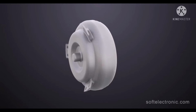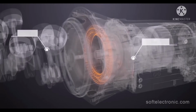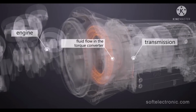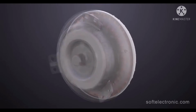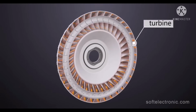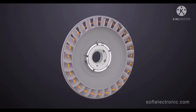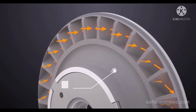In modern torque converters, there are two modes of operation. In the torque converter mode, the connection between the transmission and the engine is made by pressure of the fluid flow. The way it works is as follows. The crankshaft in the engine transmits rotational motion to the torque converter. Driven by inertial forces, the fluid is directed to the outer part of the pump. From the form of the housing and the position of the blades, the fluid is then accelerated and guided into the turbine, which makes it spin. From there, the fluid passes through the stator, changing its direction to the optimum angle to the pump blades, and accelerates for a subsequent cycle.